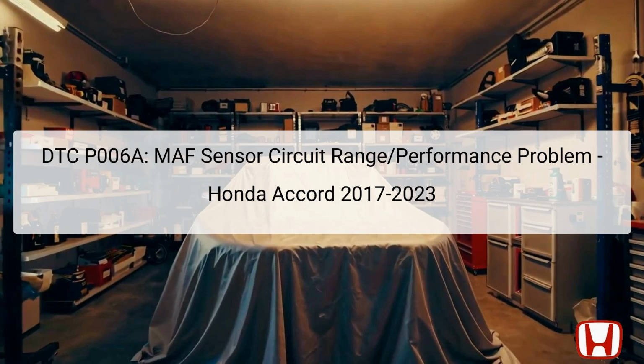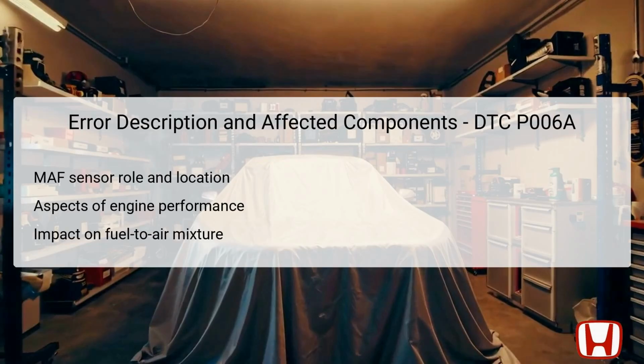Understanding the context and implications of DTC P006A is essential for effective troubleshooting and maintaining the reliability of your Honda Accord. DTC P006A indicates an issue with the MAF sensor circuit's performance, affecting how the vehicle's engine control module interprets air intake data. The MAF sensor is crucial for engine performance by gauging the volume of air entering the engine. This data informs the ECM, allowing it to adjust the fuel delivery accordingly for optimal combustion and performance.